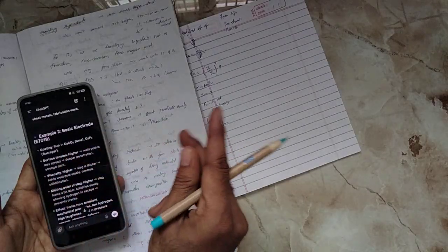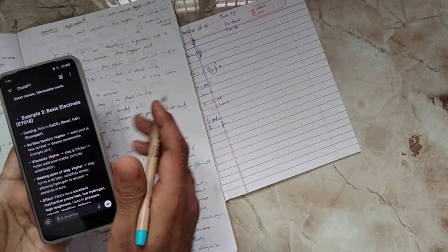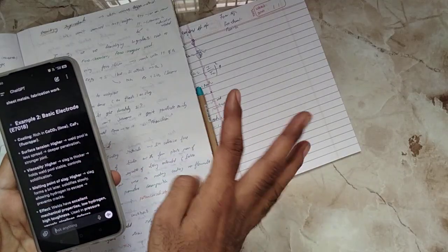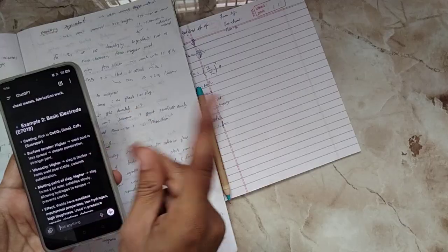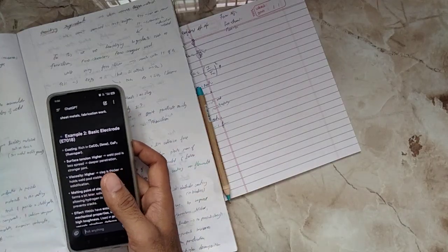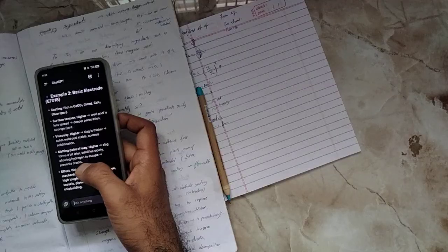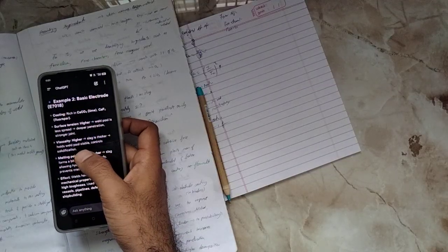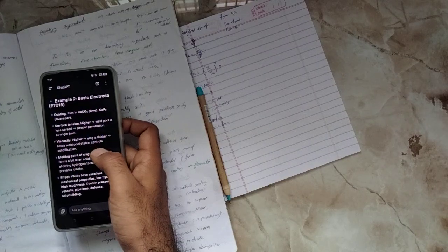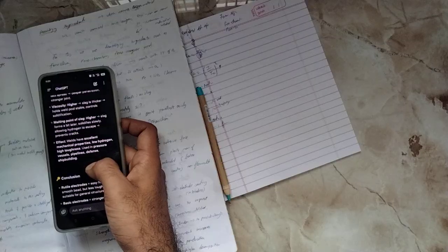Okay, next one is the basic electrode. You can see calcium carbonate and calcium fluorspar. Surface tension is high. Since surface tension is so high, weld spread is much less, and we get deeper penetration and a stronger joint. The next thing you can see is that viscosity is high, so the slag is thicker and holds the weld pool stable and controls solidification. The melting point of the slag is high, so the slag forms better and solidifies.